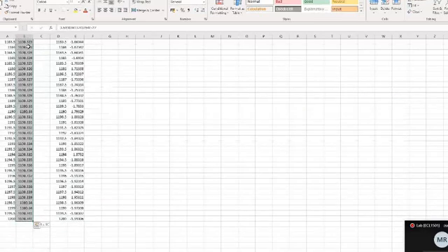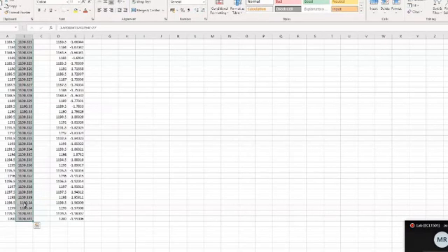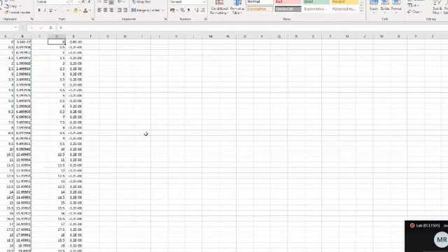You see the reverse bias voltage: when we increase the reverse bias voltage beyond 1100, the voltage drop across the PN junction is stuck at around 1100, which means this PN junction has a reverse bias breakdown voltage of 1100 volts, beyond which huge amounts of current start flowing between the junction in reverse bias. So let's copy it to a separate line.